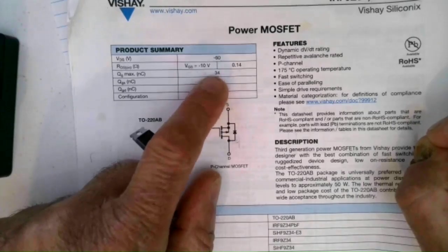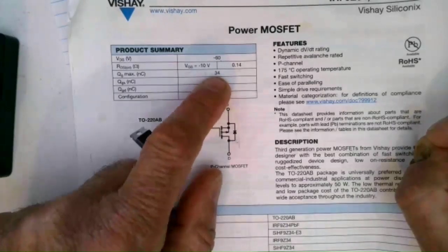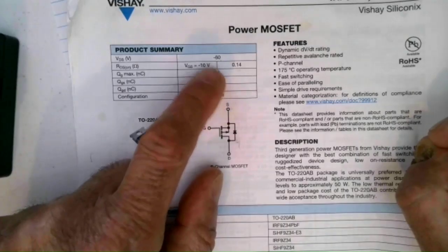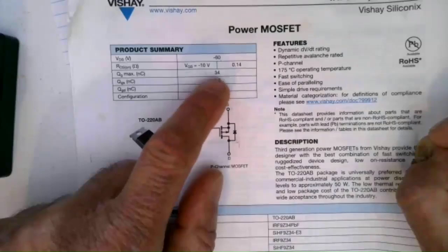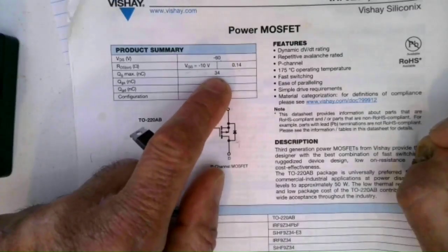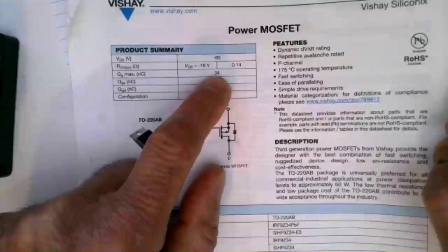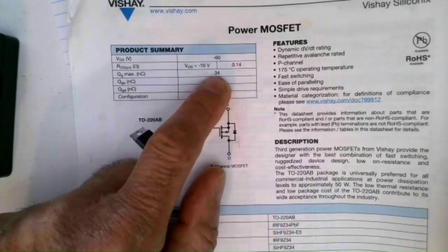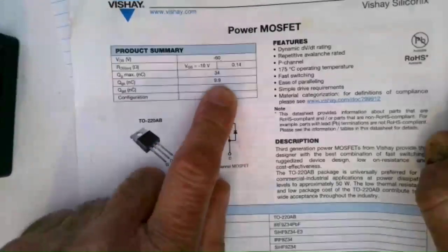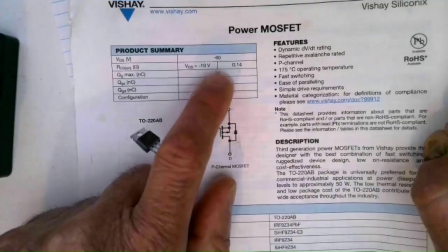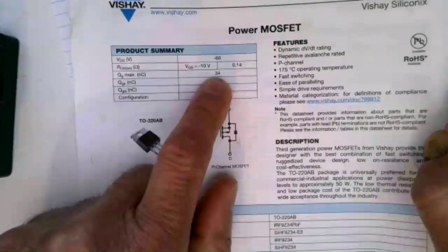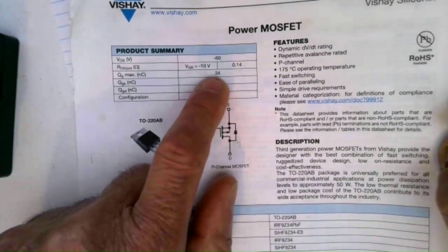In this case, you take that out when you turn the part on, and you put it back in when you shut the part off. Or I guess I had that reversed. When VGS is 0, you take charge out to pull the gate down to turn the part on. But anyway, you got 34 nanocoulombs there that come out, that the driver has to soak up when you do that.